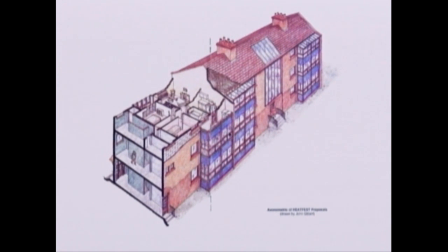The combined effect of double glazing on the outer skin of the buffer spaces and the inner glazing actually gave us U values of below 1.2. The average U value, taking into account both sets of glazing. So in fact, to get that down to 0.8 would be a relatively simple matter.